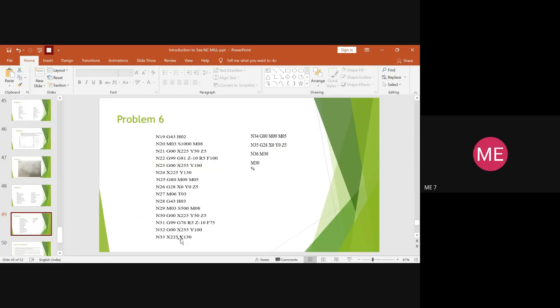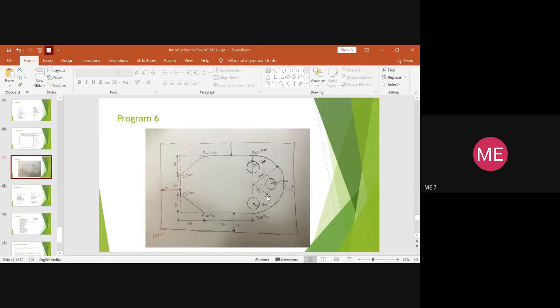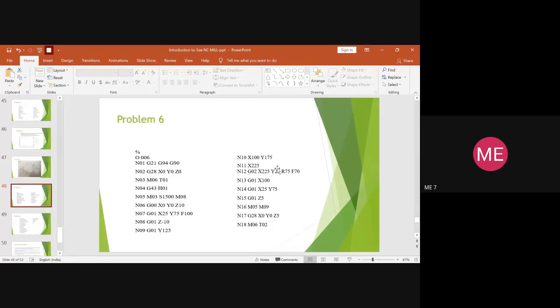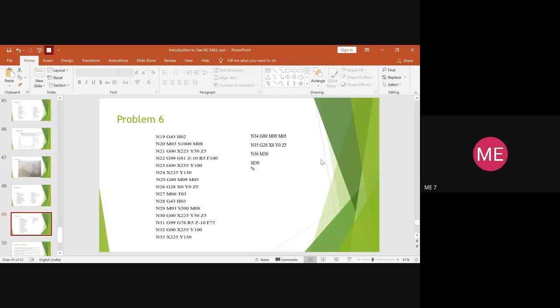Since it is a canned cycle, all the three boring operations will be done one after the other. So this shows the end of all the boring operations for the holes which were drilled out already using the twist drill tool, right? Once this is done, what is the next step? We have to turn the spindle off and the coolant off. So kindly write it as M09 and M05. The spindle gets off, the coolant gets off.